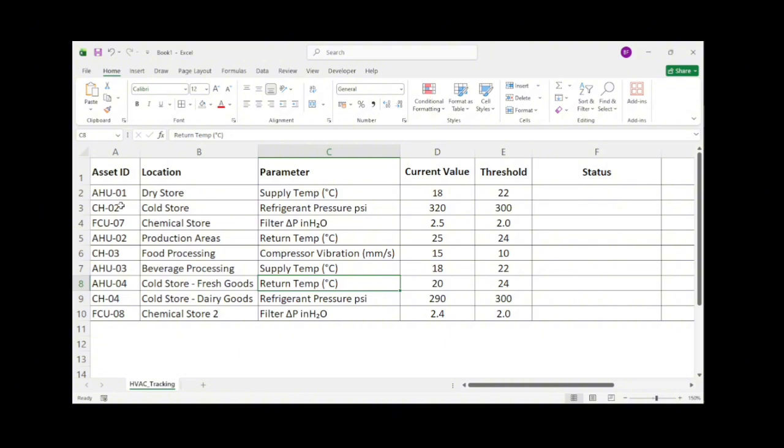Then we got the CH error or failure of the component. CH stands for chill water in system design. It's part of an error code, for example, CH02, CH05, etc. CH02 indicates a fault in the pipe temperature sensor or thermistor fault.